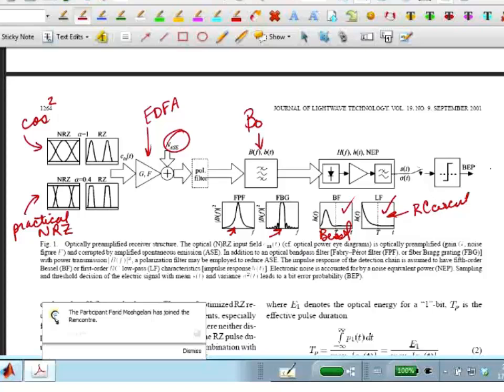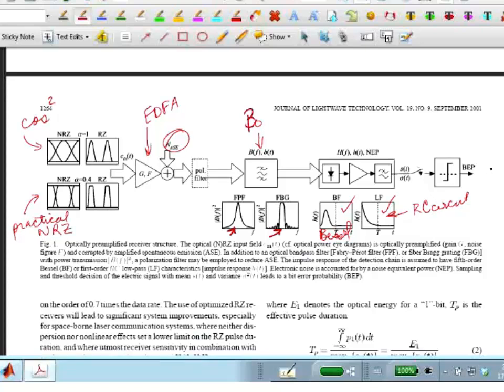That's all I had about this, just to motivate you to say that if you were interested, you could probably take our homework and actually just change the parameters to recreate this. Also, although this example is with on-off keying, filtering effects also have a large impact in coherent systems. Baud rates are being pushed, and they reach the limit of the frequency response of the components.